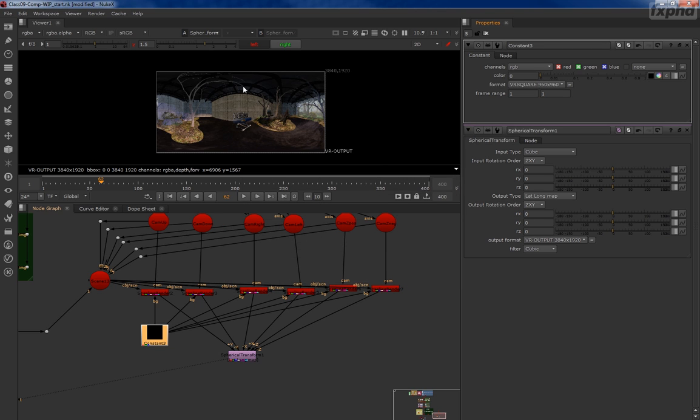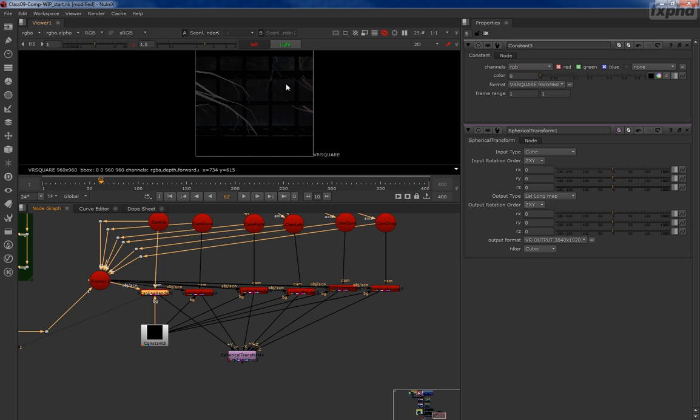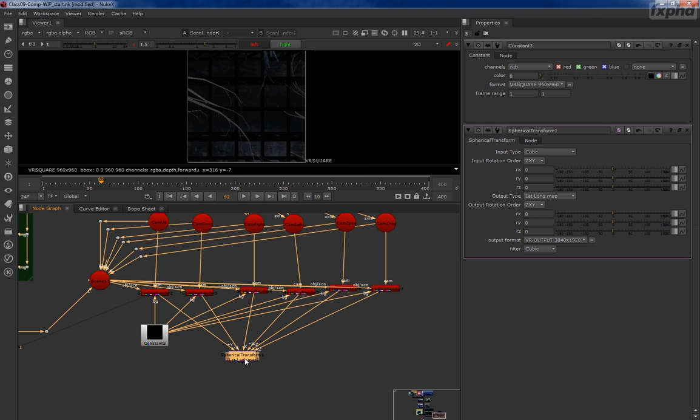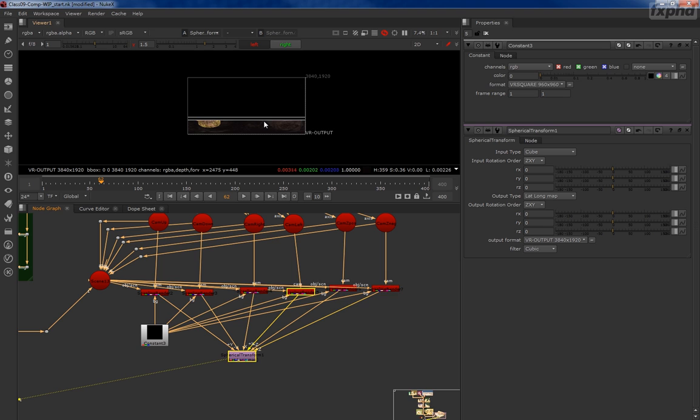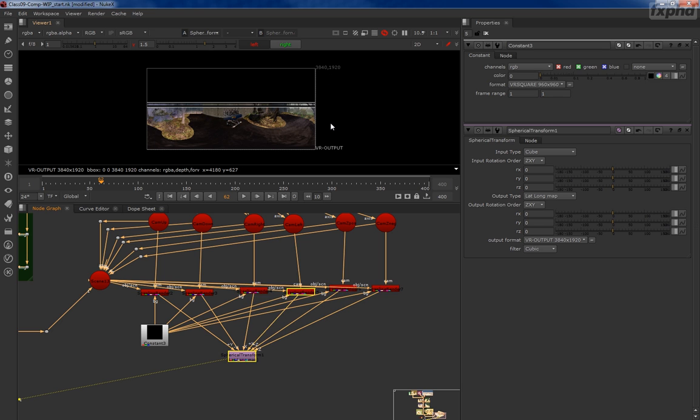All right. And that's going to optimize our rendering times because then we won't be rendering larger files than what we need for this size of VR. Now, the reason that I'm sticking with 3840 for the VR, and we're going to get into a lot more detail on this next week, is that the different platforms for viewing content, at least equatorial panoramic images, let alone stereo images, are pretty much limited to 4K right now online and across mobile devices.